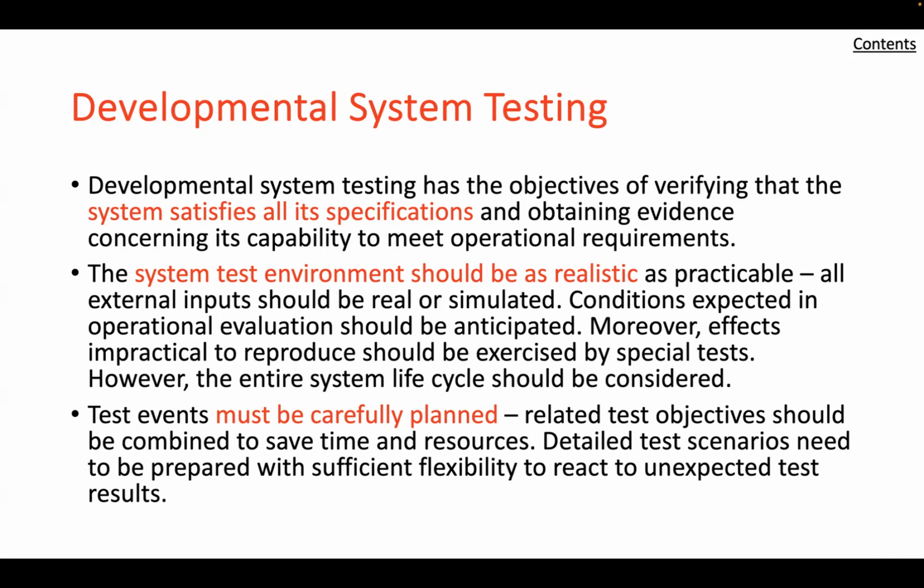For the system outputs and test points, we have three points here. So first, all system outputs required for assessing performance should be converted into measurable quantities and recorded during the test period. Two, measurements and recording should be made of all the test inputs and environmental conditions to enable correlation of the variation in inputs with changes in outputs. And three, a significant number of internal test points should be monitored to enable tracing the cause of the deviation from expected test results to their source in a specific subsystem or component.